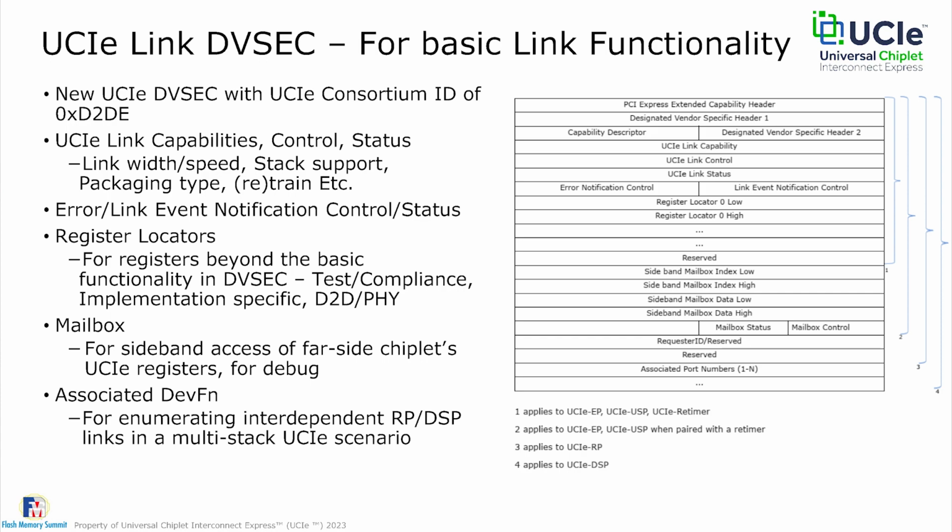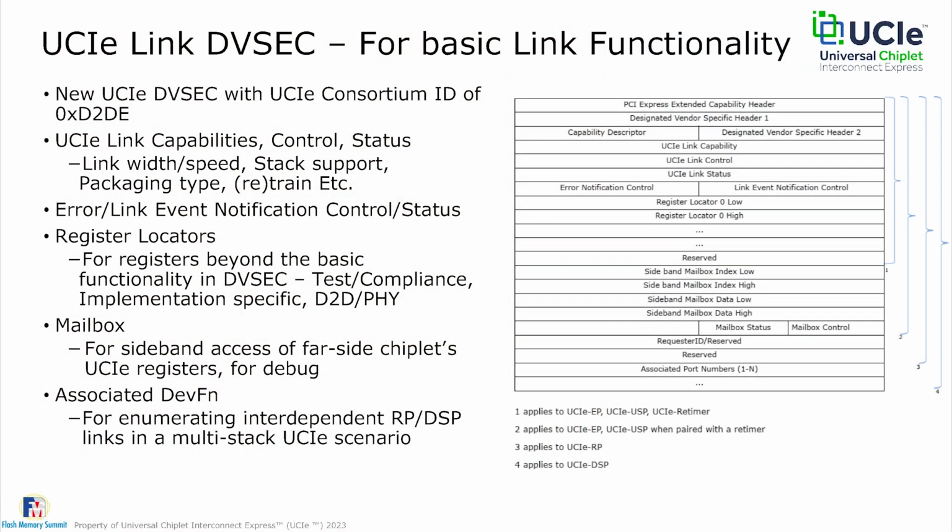That's also standardized. So if there was an error, somebody can go query it, and we want that to be standard as well, just like any other consortium. There are register locators for registers beyond the basic functionality of the DVSec, right? These are for test compliance, implementation specific, die-to-die PHY, and we'll go into the detail of what the implementation specific ones are for the die-to-die and the PHY registers.